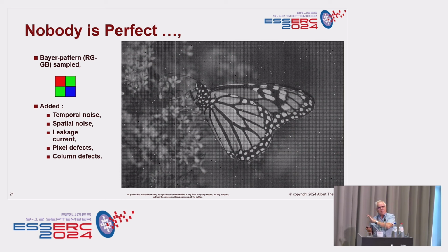Now this is an artificial image. So what I did is I added temporal noise. I added spatial noise. The difference between the two, temporal noise is what we just have heard previously. The noise of a resistor is, for instance, temporal noise. But you also have spatial noise, and that means noise that is changing from pixel to pixel. Pixels are analog devices, and they are not equal to each other. Maybe they are equal to each other to 99.99%, but there's still something that is left there.